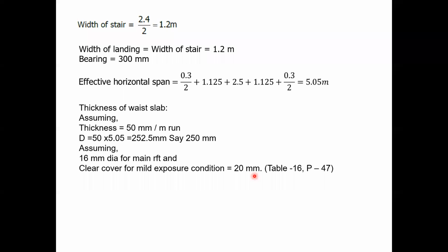The effective depth, small d is equal to 250 minus half of the dia minus the clear cover. Any doubt in this? No, sir.